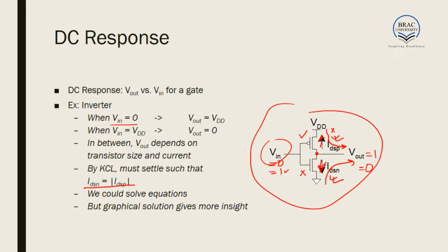If we are to consider them equal, one of the currents must come inwards and the other must go outwards. Here the current generally flows from VDD to ground, which is the opposite direction of IDSP. That is, it's the direction of ISD, from source to drain. As a result, we write the modulus of IDSP to get a positive current and equate the two.